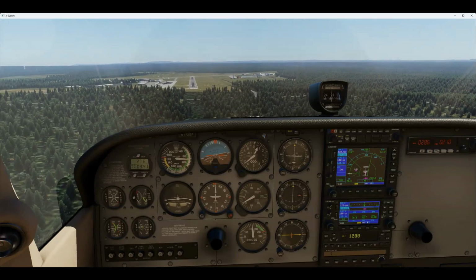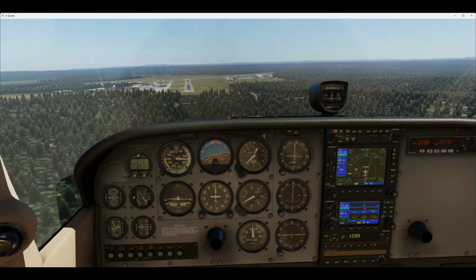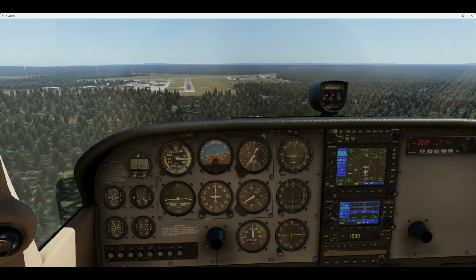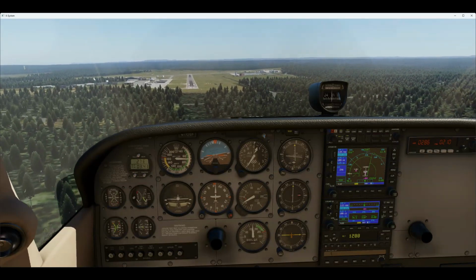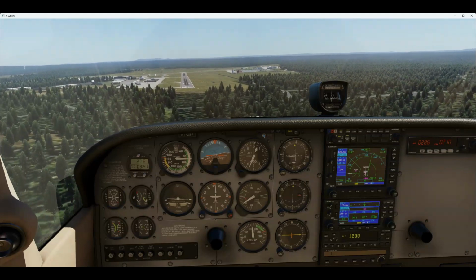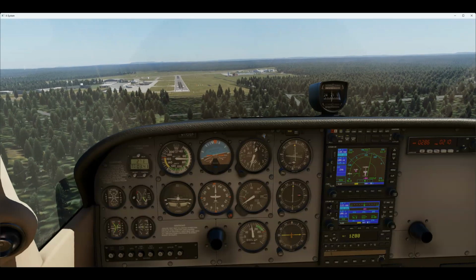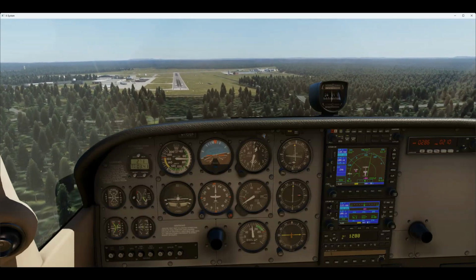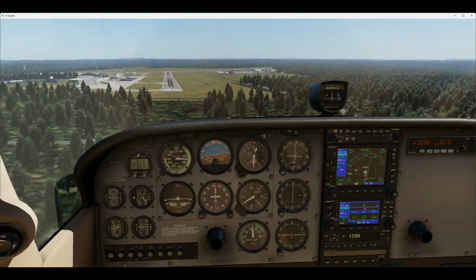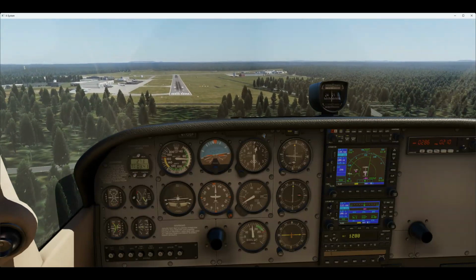But now I'm less focused on the GPS. I'm looking outside. Focused on just landing. The scenery's pretty terrible, right? Because it's not a proper one. It's just the default one. It's telling me I'm a bit high on the PAPIs because it's now 3 whites and 1 red. So I can reduce power a little bit. In a small aircraft, it's okay. 3 whites is not a bad thing because we can get down pretty quick.